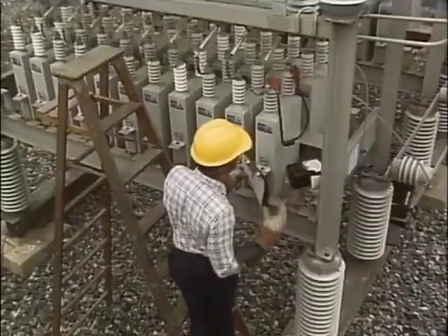Substation capacitors are not typically tested on a routine basis. Usually they're only tested when there are indications of trouble, such as blown fuses, or if the capacitors have been exposed to unusual conditions, such as severe weather. In general, there are three parts of a capacitor that can go bad. These are the internal bleed resistor, the capacitor insulators, and the internal capacitive elements. In this part of the program, we'll look at how to test the bleed resistor and the insulators.